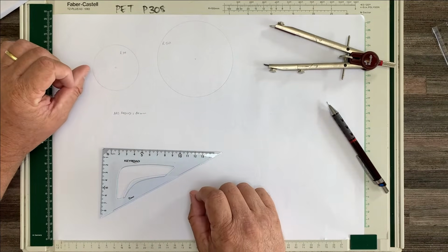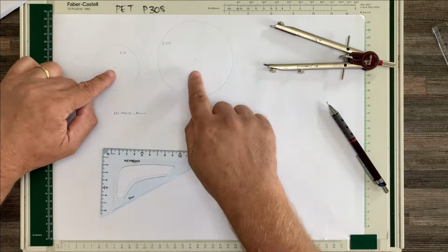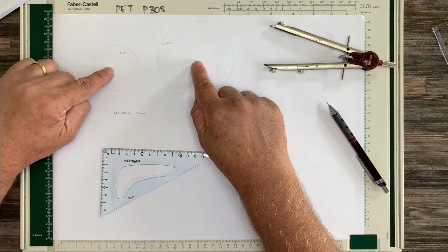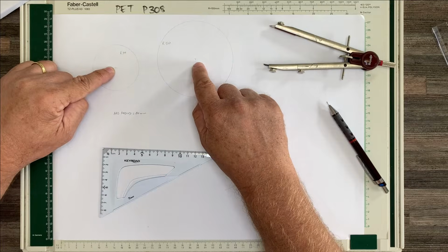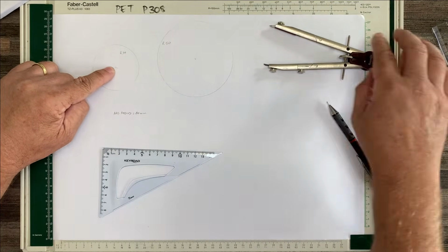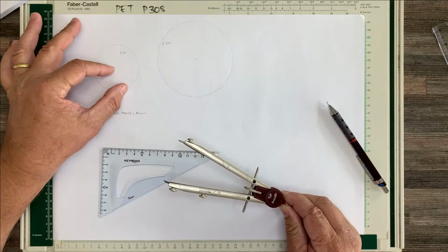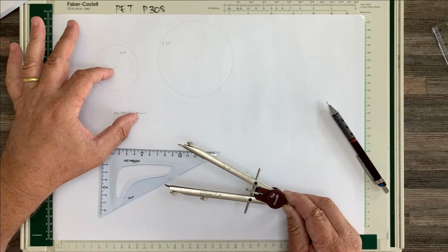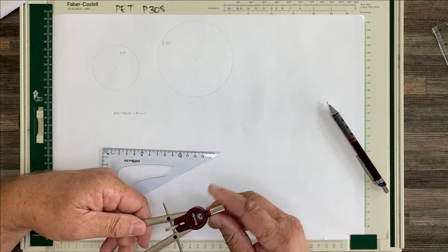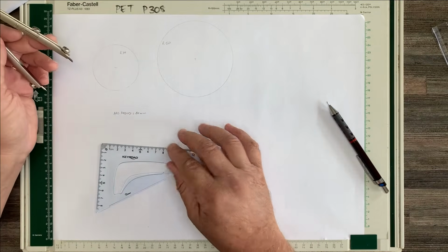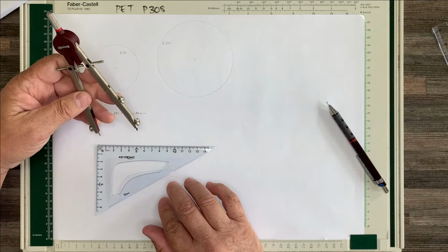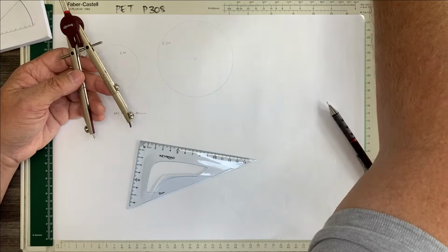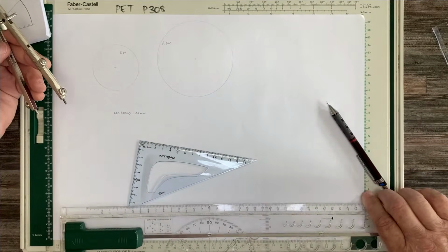The way we determine the center point is by adding the radii together. So we're working from two known points. The only two known points on the drawing are the center of the radius 30 circle and the center of the radius 50 circle. So if we take that center and we add on 80 millimeters, we can draw an arc, and we know that the center of this radius will be on that arc somewhere. So if we take 80 and we add 30, we get 110. I have to use my longer ruler.